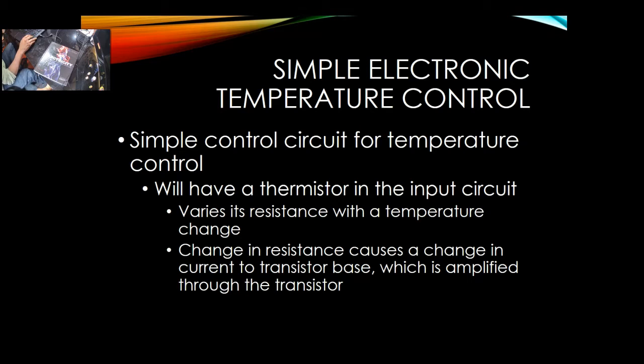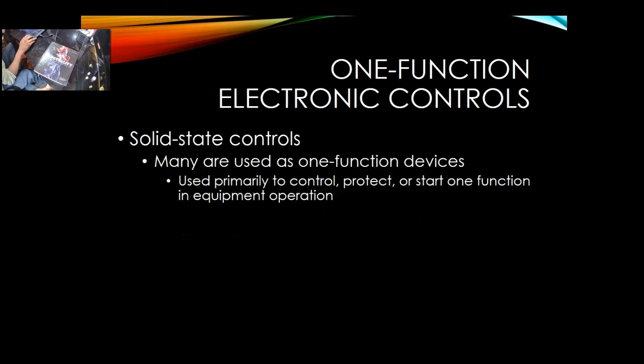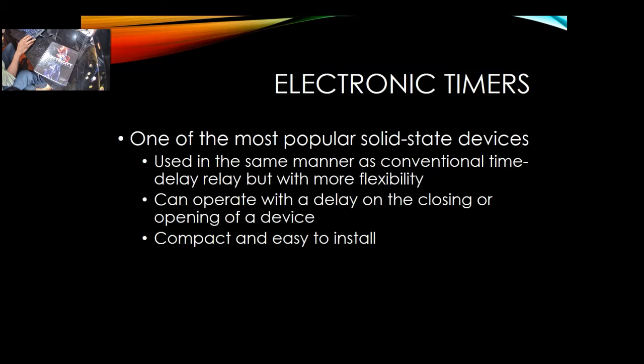For heating, we use thermocouples. We have a lot of solid states, not a lot of moving parts. The primary controls and the aquastats, the old ones had moving relays with mechanical linkage. The new ones are mostly solid states, and sometimes you don't even see the relay. So solid states with no moving parts have become more dominant now.